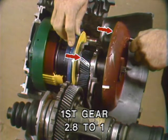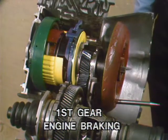The gear ratio of 2.8 to 1 can be increased to as much as 5.6 to 1 with the torque converter at full stall. Remember now that what we've seen is freewheeling first gear. The one-way clutch holds when power is applied, but freewheels in the coast condition. For engine braking, as with reverse, we need the direct clutch. Let's look at engine braking.